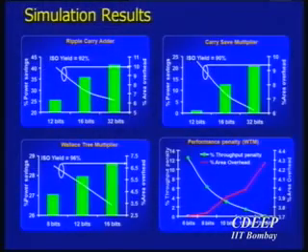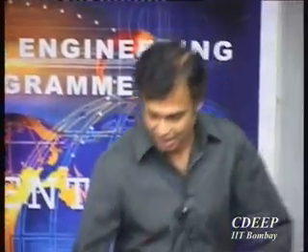One other thing that you have to be careful about, which I didn't mention, is the size of the decoding circuitry. The size of the decoding circuitry has to be small because you have to turn off the clock to your latches or your flip-flops before completion of that critical path.